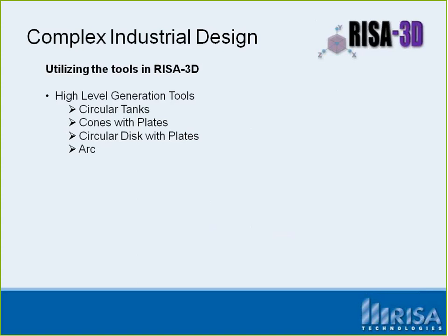We'll also be using an arc to help develop several different things for our tank model. We'll also be using our append feature, which is something available in RISA 3D that allows us to bring one model into another model. We'll also be using our selection tools with very complex, three-dimensional RISA 3D models. You're going to want to use these selection tools to help guide you through the model, select portions of the model, make modifications, and work with all the different tools you have there. Selection tools become very, very important on a large model.